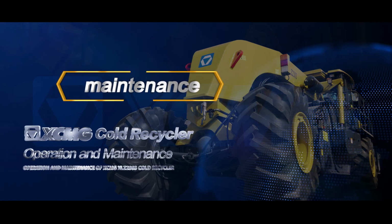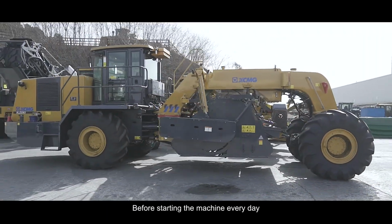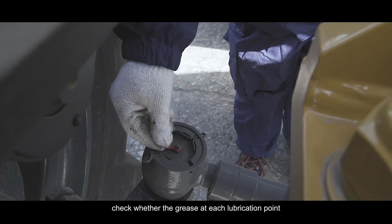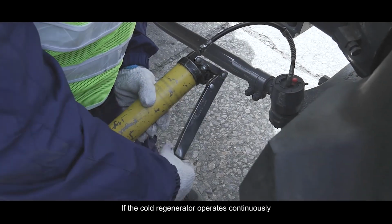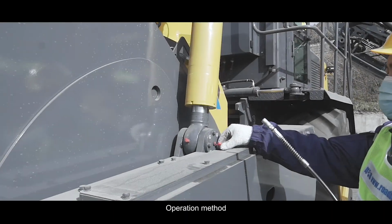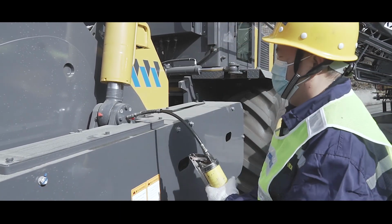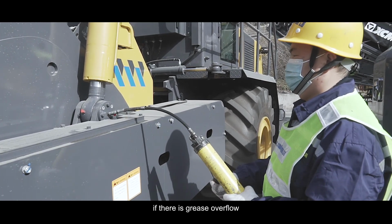Maintenance. Vehicle lubrication. Before starting the machine every day, check whether the grease at each lubrication point is sufficient to ensure that the bearings are normally lubricated. If the cold regenerator operates continuously, the use of grease should be checked during the intermission. Operation method: refill grease for each bearing from the filling port. Pay attention to the corresponding bearing seat. If there is grease overflow, stop filling.